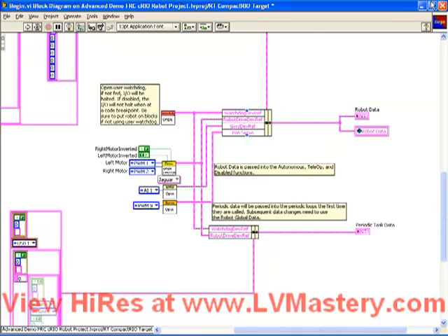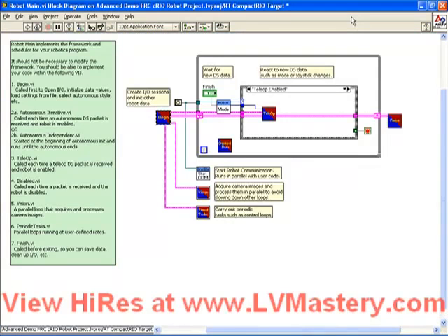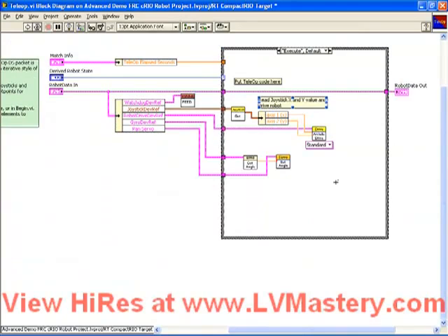So those of you who have been watching really closely might have seen where it got written. Well, let's just return to the teleop VI. The code that we just added was in the execute state. Remember that in the Robot Main.vi, we have a block which is determining what state the robot's in, and that's feeding that in to this sub-VI. In normal operation, it's going to be sent the execute command, and that's why we put our teleop code here.